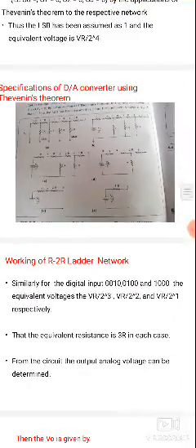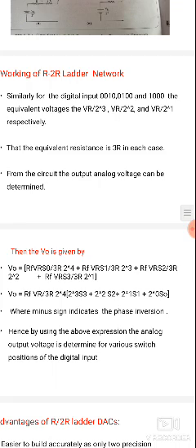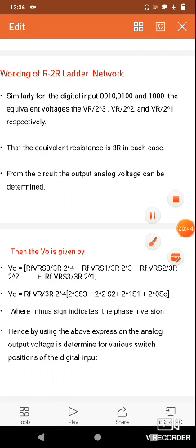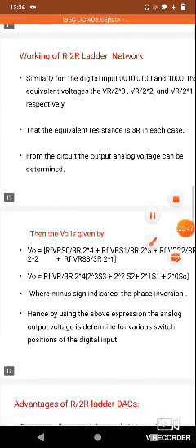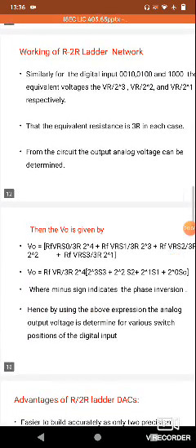So what is Thevenin's theorem? Thevenin's theorem states that it is possible to simplify any linear circuit to an equivalent circuit with just a single voltage source in series with a resistance connected to the load. We use Thevenin's theorem because it provides an easy method for analyzing circuits in which the load changes value during the analysis process. It provides an efficient way to calculate the voltage and current flowing to the load without having to recalculate the entire circuit over again.